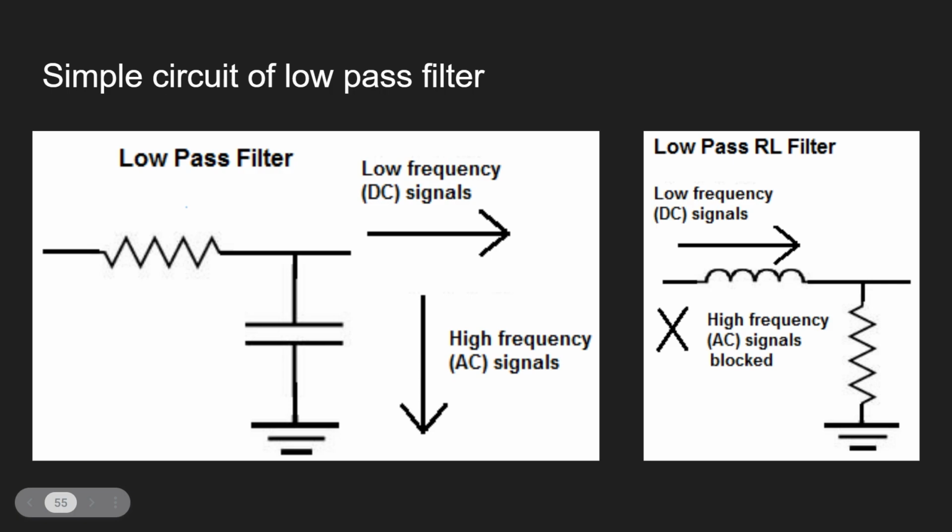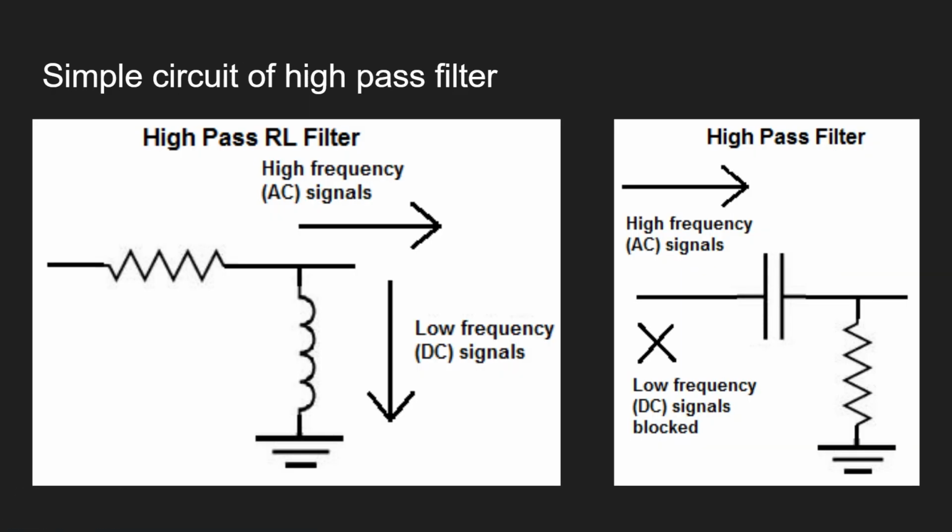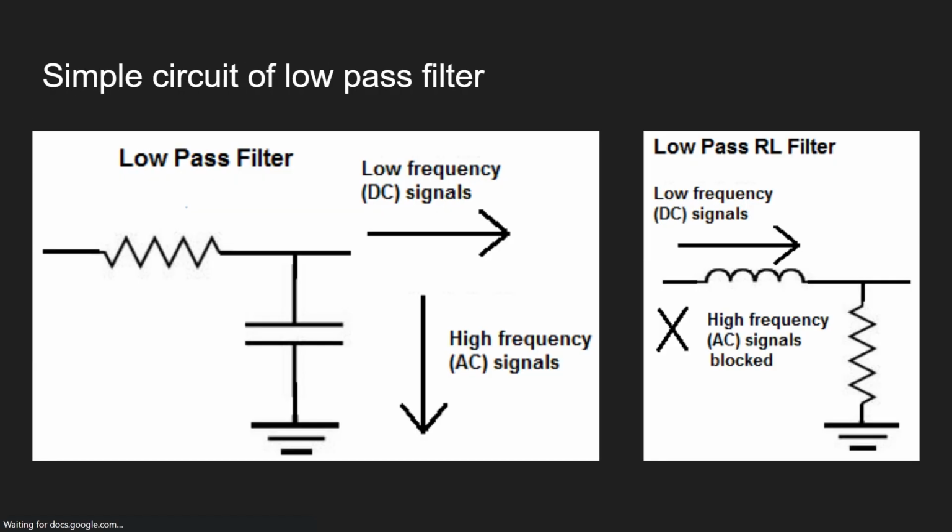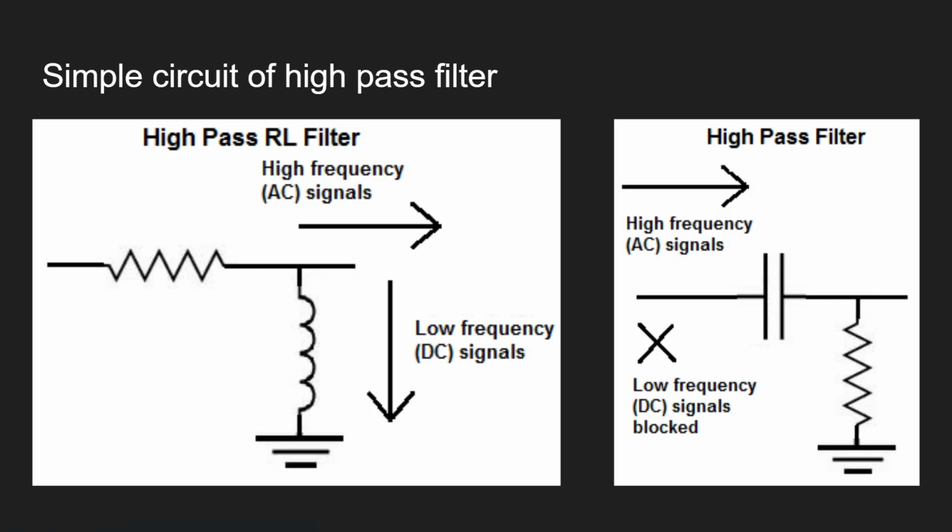So you see that if you compare this graph, compare the left hand side. The load is here, right? Low pass filter, the load is here. That's why I have to use the same setup here for you. If we just change this part from capacitor to inductor, it can be changed from low pass filter to high pass filter. Okay, but this one is a flipped design. Trying to block the signal instead of grounding the signal. This part, all of them are grounding the signal. So if you can't memorize this one, just use the left hand side.